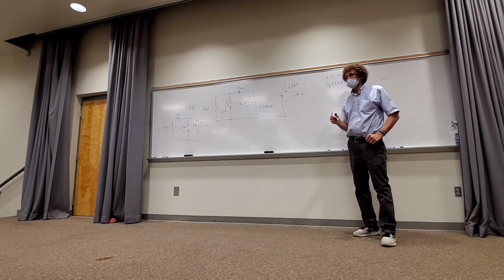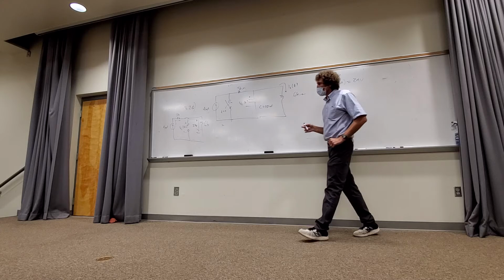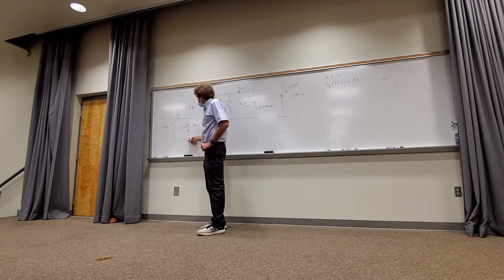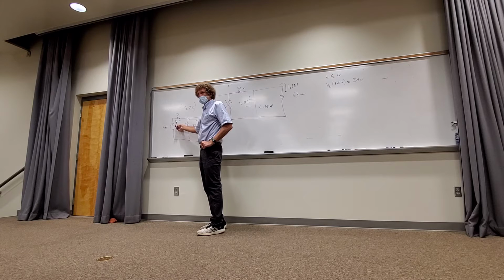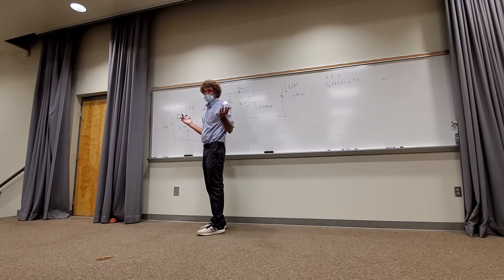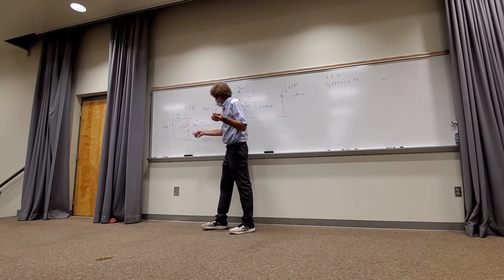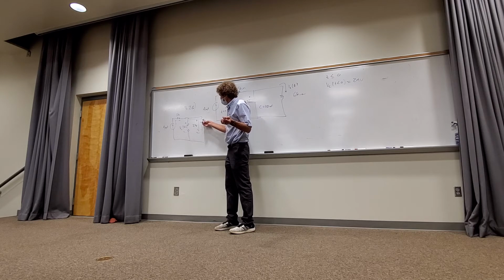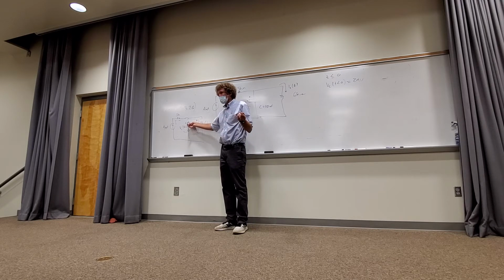I think I'm confused because I'm not understanding why we ignore the 3K resistor. Why do we choose? What are we after? We're after the voltage across here, right? Yes. So could we go this way to get the voltage? We would have to go from here to here, right? Why can't we go that way, anyone? Because you can't go across the voltage. We don't know the voltage across that current source. You can't sum voltages through a current source. But we know this voltage, so if I start at the negative and go here, it's an increase of 24 volts at this point. Y'all with me?